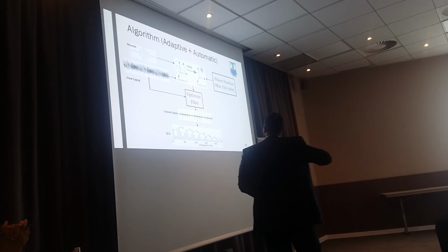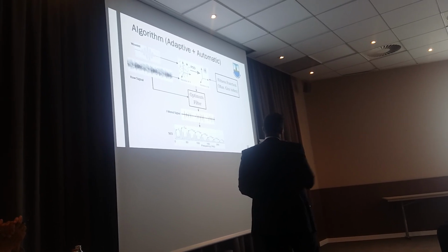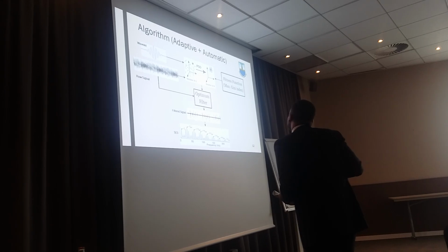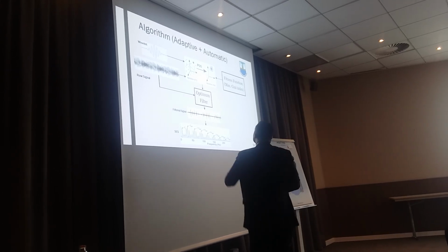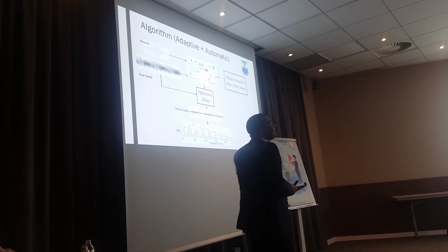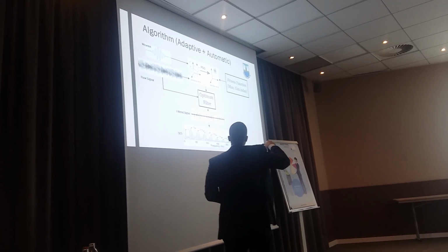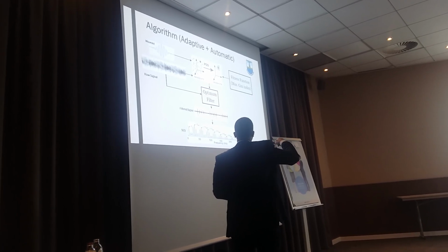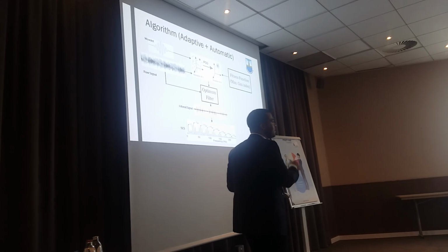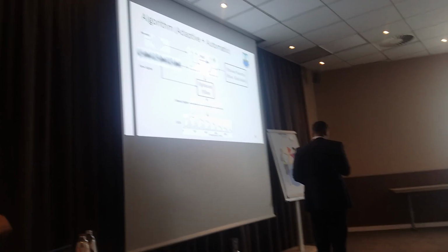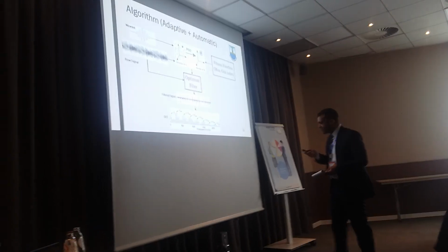This is the filtered signal, and this is the raw one, using an optimal filter based on Gini index. And finally, to diagnose the fault and know its location easily, we transfer it from the time domain to the frequency domain, and we determine the envelope of it in the frequency domain. And we will see the benefits of that in upcoming slides.